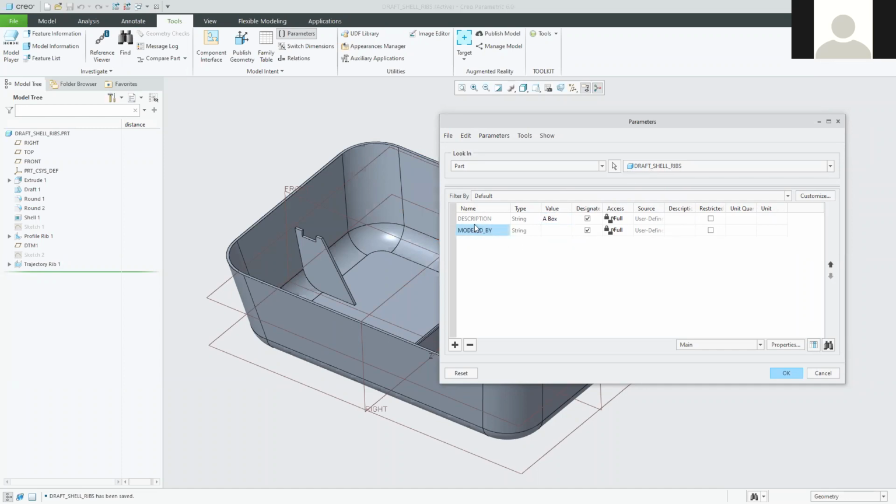It also, by default, provides you with one which is intended for the person who created this part file to kind of sign it. So normally the done thing on engineering drawings is you put your initials in there. And again, these are really useful. They're useful for keeping track of who claims to have modeled something, but they're also useful when you come to produce drawings. You can access this data from the drawing. You can enter it automatically into a box on the drawing. Who was it who modeled this part? And there's an initial that just pops up there. So those are the default ones, and you can add your own data into them, into the values column.